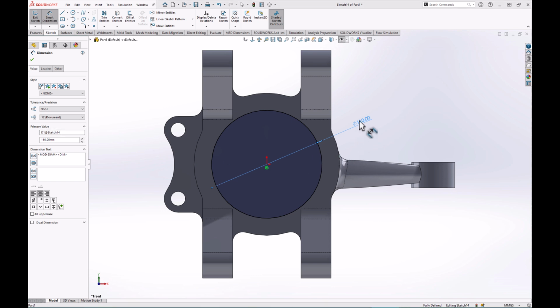then the way that you would do that is, once you've applied a dimension to it, if you go over to the left here whilst you've got the dimension selected like I have, and then you have a look in this menu, you've got some options here. You can just put some manual tolerances on this dimension, or probably more in keeping with using standard fits, you can specify a fit. So let's select the option where we can specify a named fit.